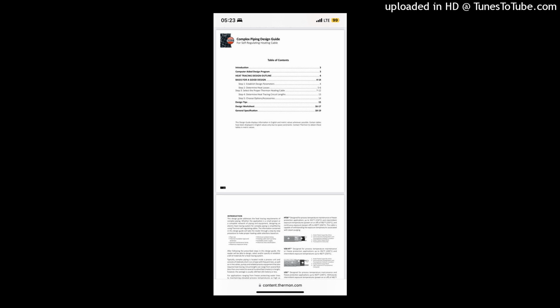RXX52, designed for applications where the watt density requirements preclude the use of the standard range of PSX cables. 1. Nickel-plated copper bus wires. 2. Radiation cross-linked semiconductive heating matrix. 3. Polyolefin dielectric insulation. 4. Tinned copper braid. 5. Polyolefin or fluoropolymer over jacket.